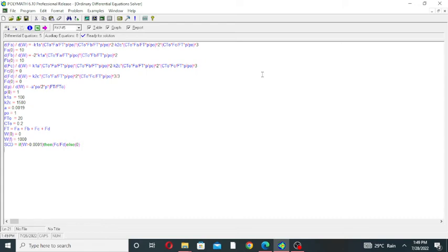So now I am solving it. This equation is for selectivity, because selectivity is equal to FC divided by FD. But if FD is zero in this place, then the selectivity of component C with respect to component D will go to infinity, and it will crash our POLYMATH.